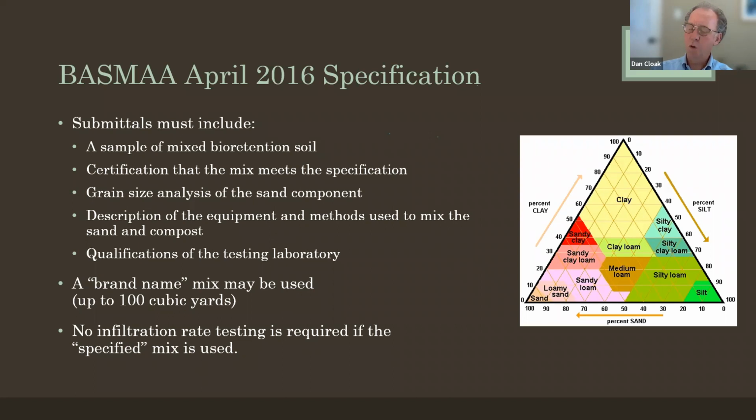BASMA created a form for checking off that each of the detailed requirements in the specification are met. We managed to negotiate into that spec and into the MRP requirements by extension that, particularly for smaller projects, you don't have to have a laboratory test for that particular project. The yard or the soil supplier can say, yeah, that's our regular such and such mix. We send it in every 120 days.